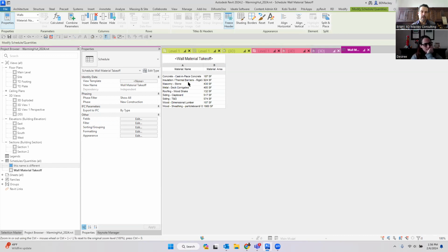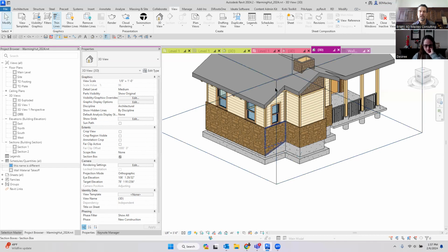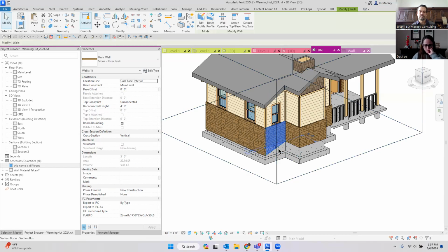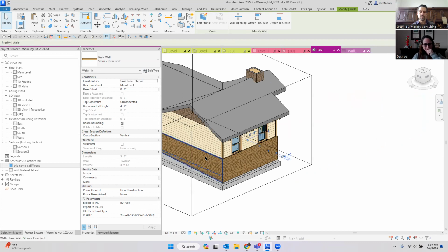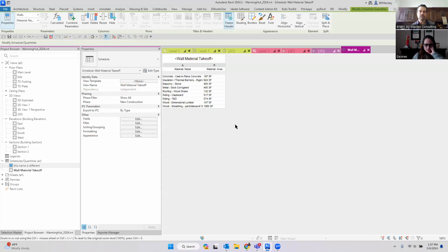And that was probably my stone. So right here, you can see it's 430 square feet. If I were to come back here and say reset, and we'll do this one too, because that was going to be much greater square footage. Reset, go back to my schedule. I should no longer be at 430 square feet, but something less. Where is that? Masonry stone, 405.